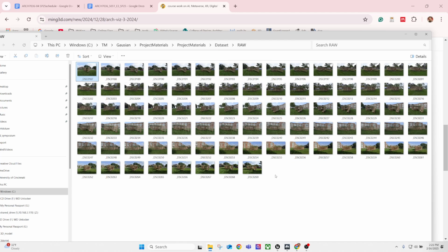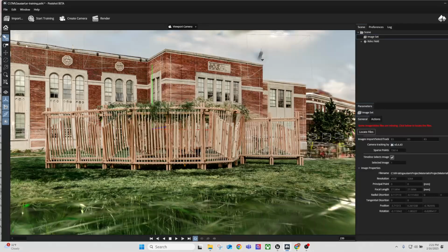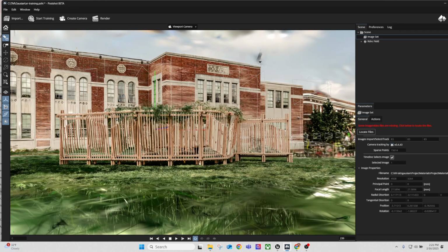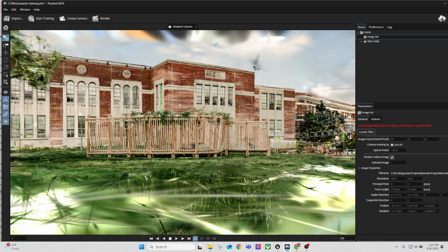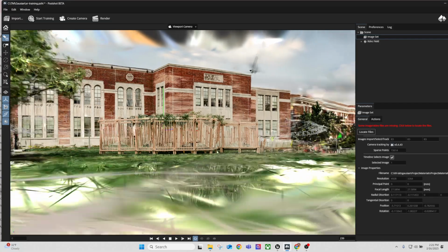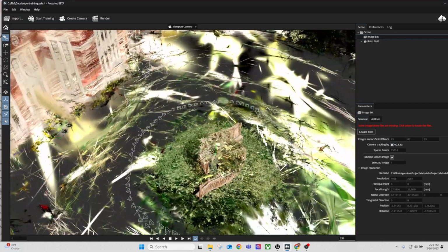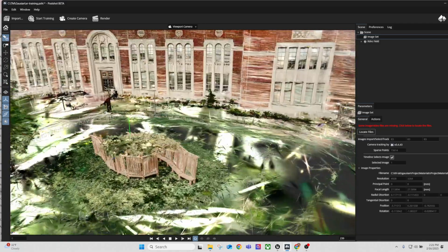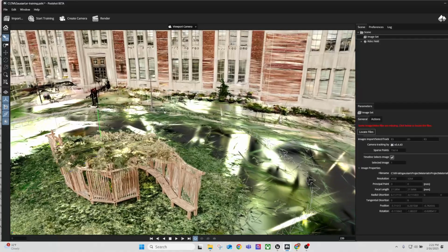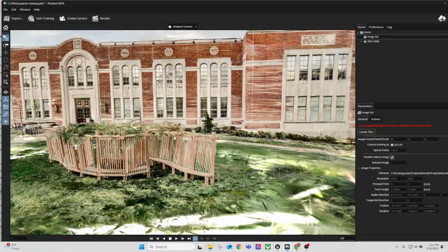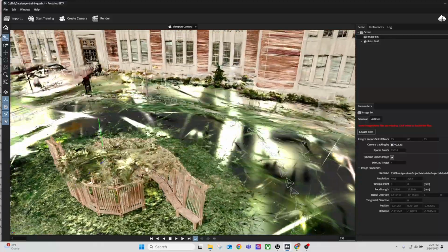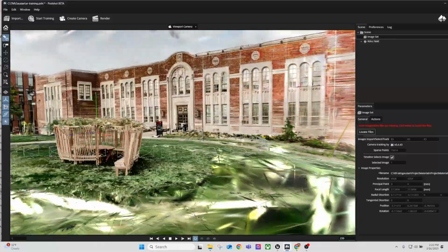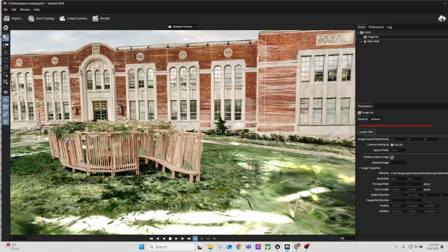Once you have all of these images, you can use a program called PostShot. You can Google it, you can find it. You load these images as training material, set up the training, and then start training. After the training, depending on your GPU power, you are able to create a 3D model of the Gaussian splatting. It will generate all of these camera locations based on the photos, so you have this kind of free perspective. You can see the entire 3D model after this.